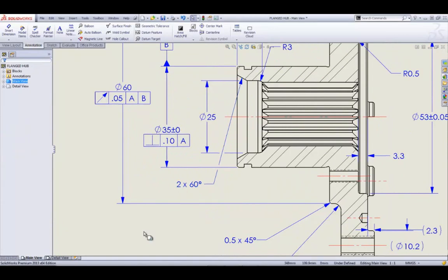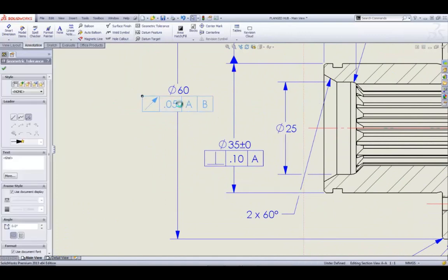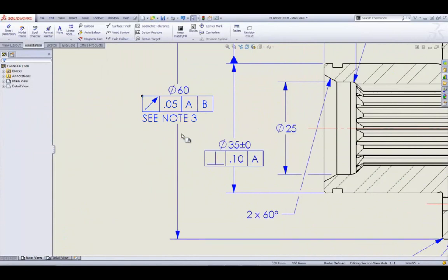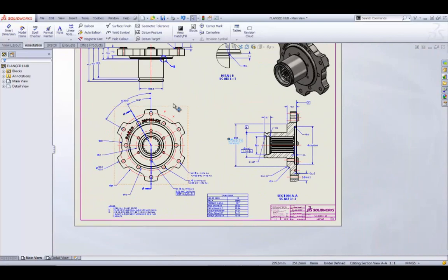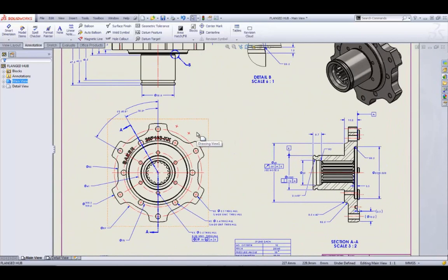Many times it's the small things that really make life easy. One of the other things they have done, if anybody's doing GD&T, and I know we have a lot of people that do, is they have given us a below the frame. So now we can go in here and type something in like C note 3, and you will see that it appears in here. It takes the leaders and shortens them up. It's one of these small things that many people are fighting with that we now have as an option. So a couple of new things right here that we can work with.